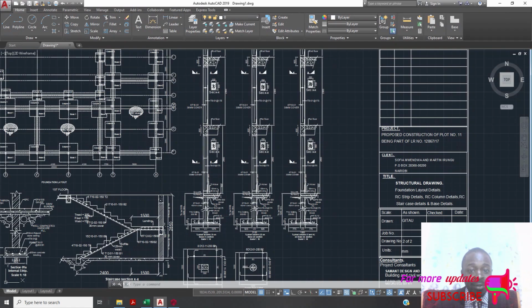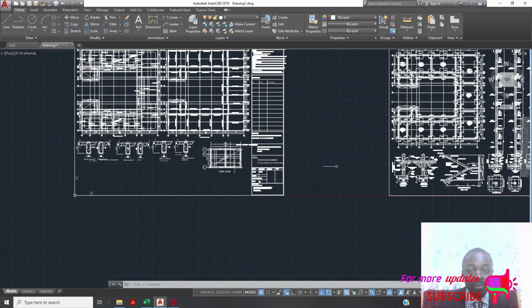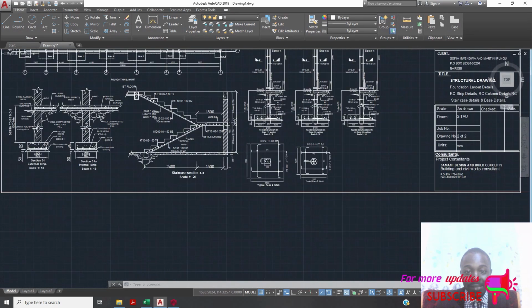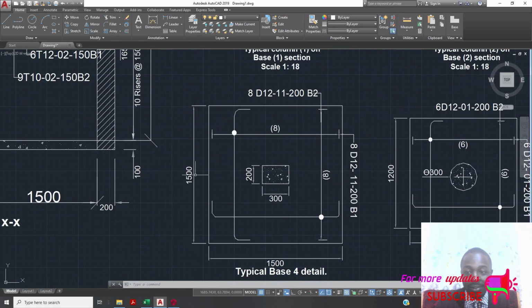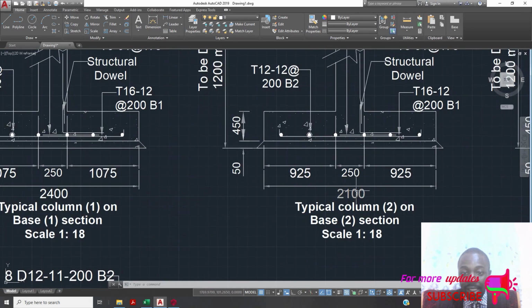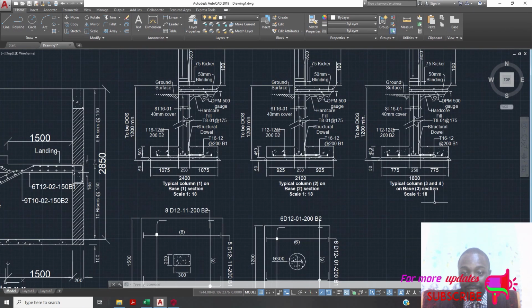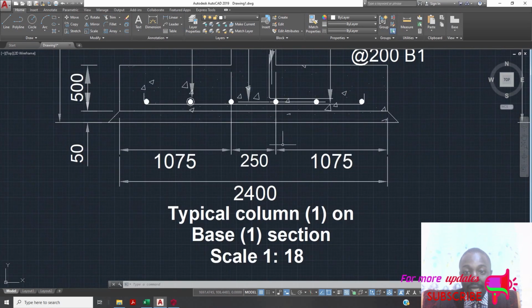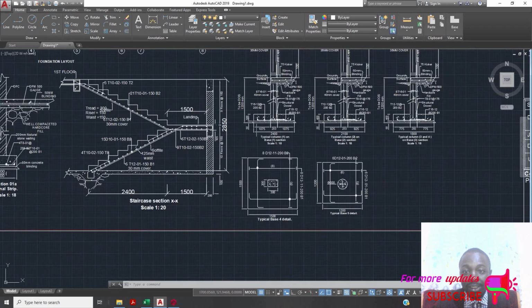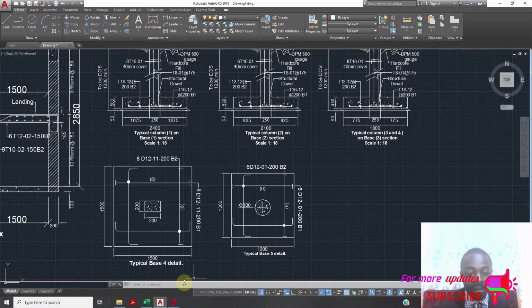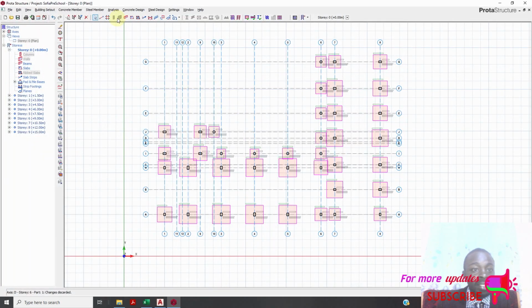So it's like you are suggesting that this was approved by mistake. As you can see, the footings here are very just 15, 12. How many types of footings? This one is 2100 by 2100, 1800 by 1800, 2400 by 2400, and just using T16 and T12. T16 and T12. There is no T20 in these footings, but here, if I can